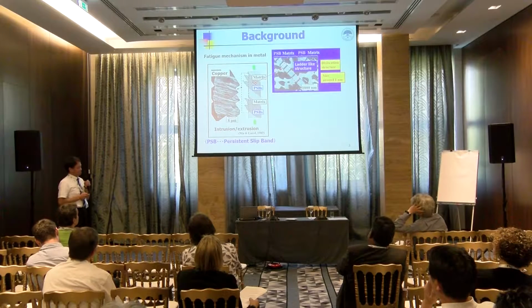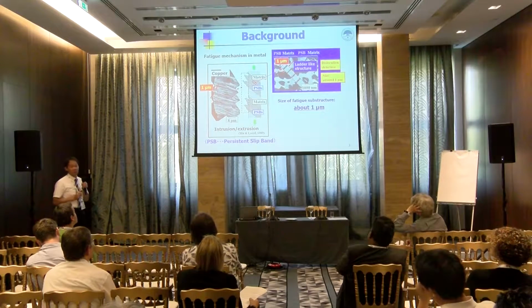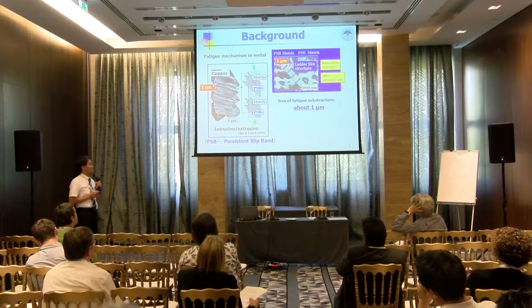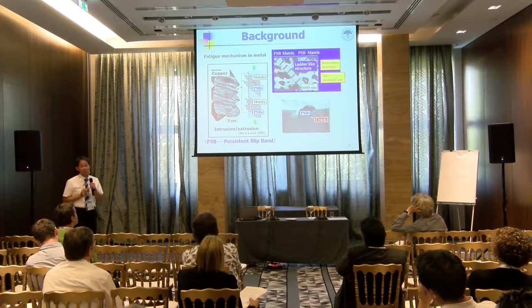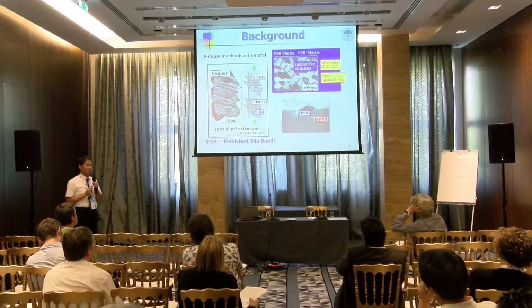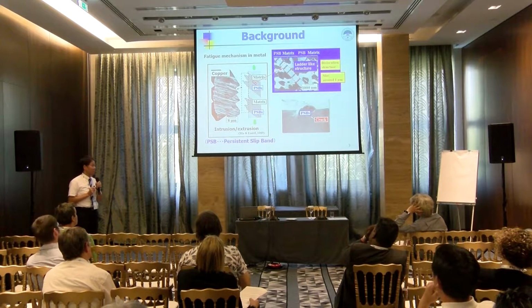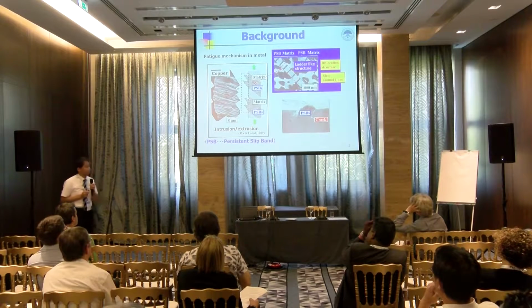It is known that the width of this fatigue substructure is approximately 1 micrometer, which is independent of material size. And it is also widely known that the PSB plays an important role in fatigue failure because the PSB acts as a preferential crack initiation site.